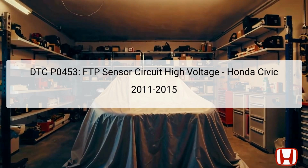The DTC P0453, or Diagnostic Trouble Code P0453, refers to a fault within the fuel tank pressure (FTP) sensor circuit of the Honda Civic models from 2011 to 2015. This particular code indicates a high voltage signal issue from the FTP sensor, which is a crucial component in managing the evaporative emissions control system.